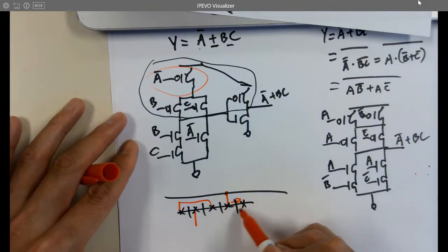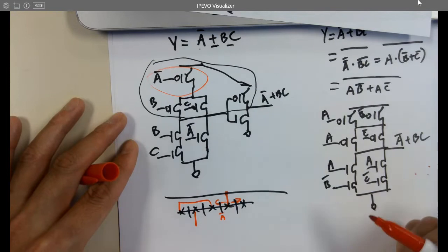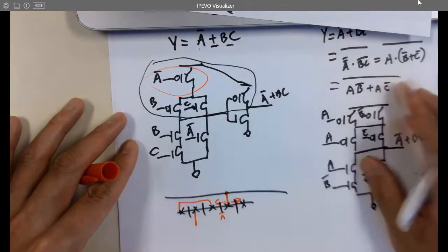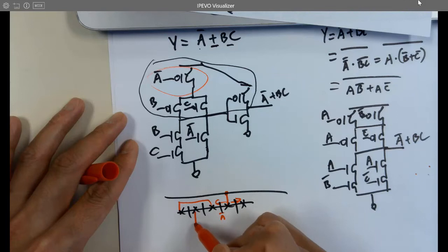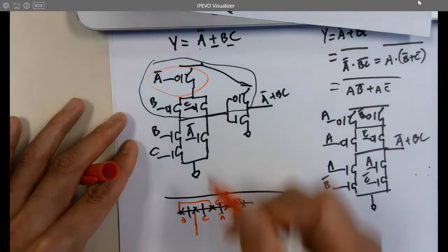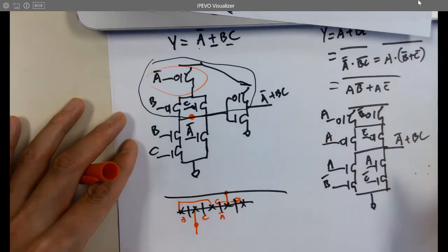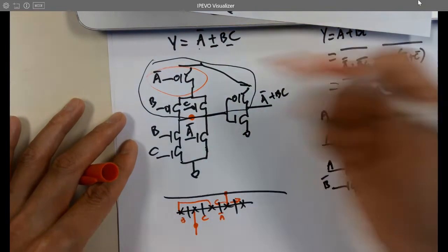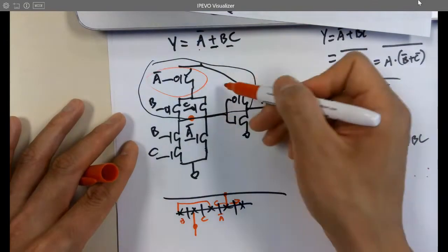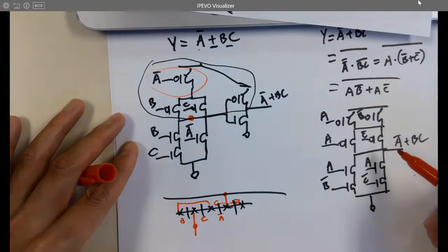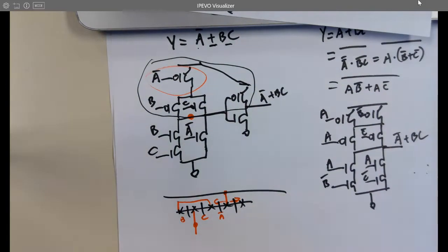So this one is the inverter's PMOS, right? No problem. And this one is a NOT. Oh, I didn't swap it. Anyway, sorry. So this is a NOT, and then here 2 in parallel, and this is B, this is C. And here's a wire here. So this guy just got lucky. You're still able to do it. But if you have more transistors, sometimes you just couldn't put everything in one line. All right?